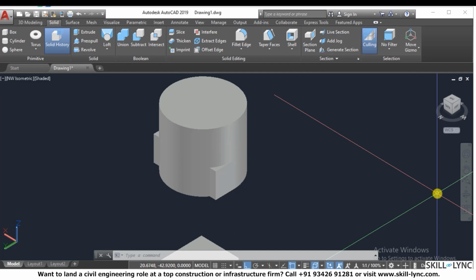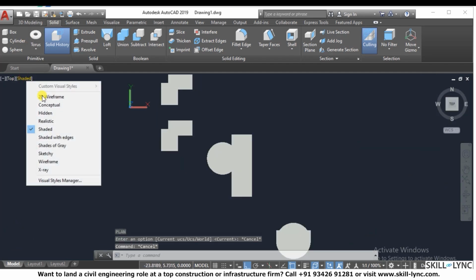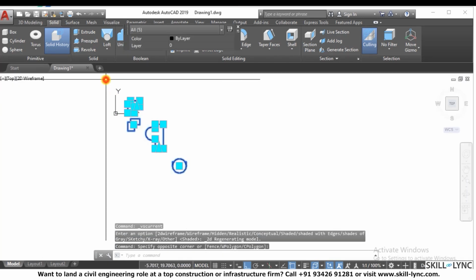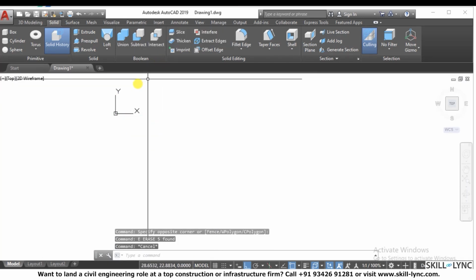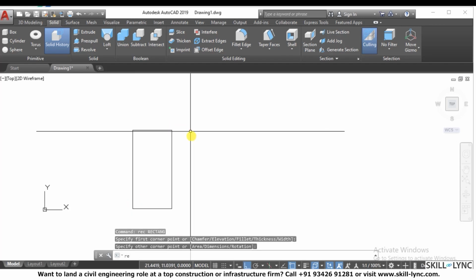So union is basically uniting two surfaces or two regions or two solids to be one surface, region, or solid. Next Boolean operation is, so I can go to the 2D plan, the subtract. So what we do in the subtract, we have the two regions.